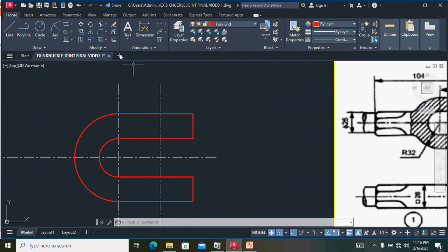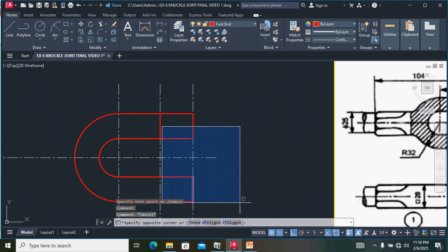Okay, select this point. Okay, we have to select this point, take offset. 24 mm diameter means we provided 12 mm. Type enter in the leftward direction and then click this point in the rightward direction. Okay, and then click escape. Just click this point and delete.